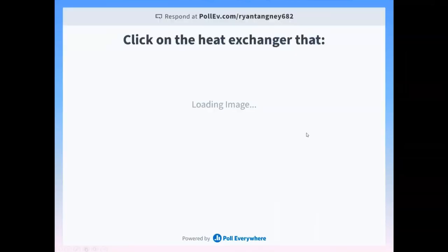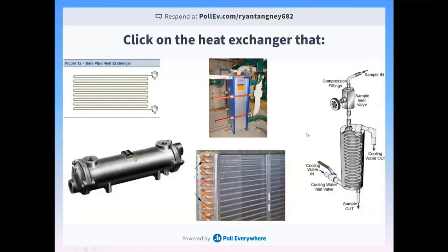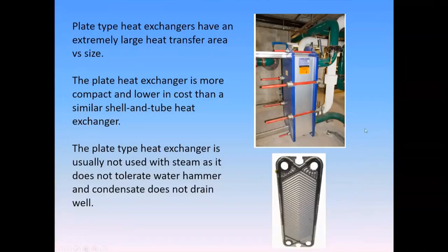And I guess if you have any leakage with them, you might have to take them all out and change all the gaskets. That can be the case. So they're reasonably low maintenance until you have the point where you do need to maintain them, and then it is quite a bit of work to reset them and reseal them. So yeah, you hope that you don't have any leaks, but it is a pretty big undertaking if you do have leaks with it.